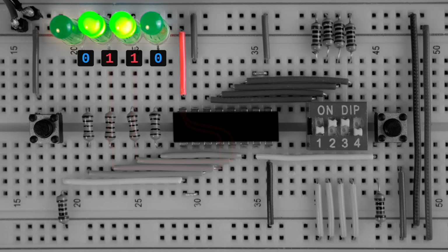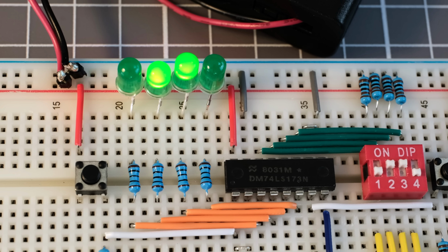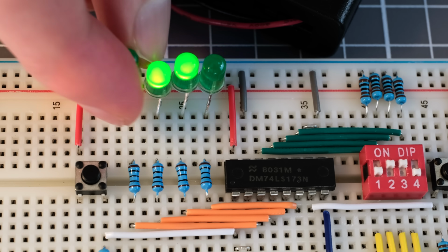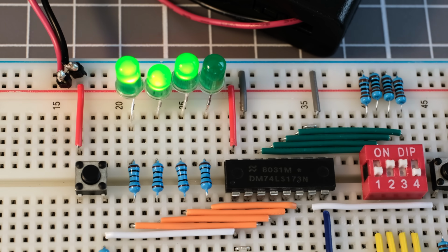On the other hand then, a 0 represents a connection to a low voltage, something at least close to 0 volts. So I'd imagine that the lights that are off should be connected to the ground pin inside of the chip. We can confirm if that's actually the case by just grabbing one of the lights that's off and turning it around to connect to the power rail up here instead, and we can see it does light up, so it must be connected to ground on the other end.